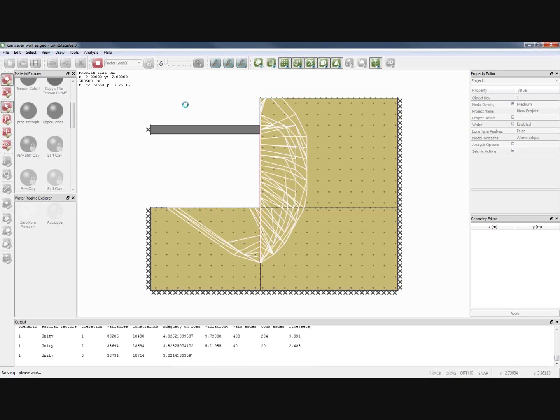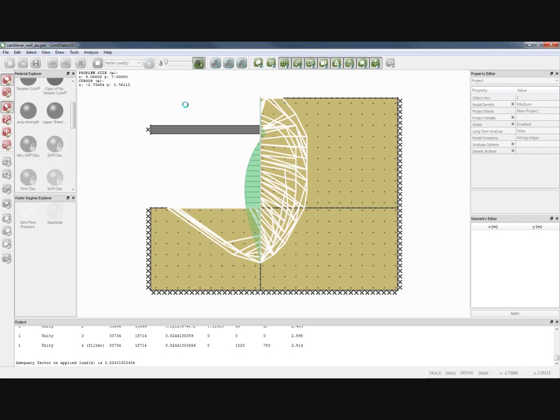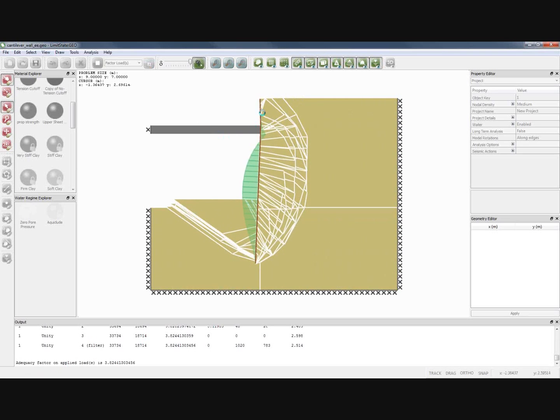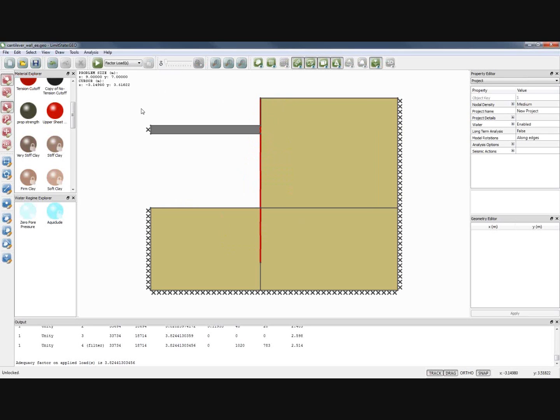And what happens then is that upper bit of the wall stays vertical, essentially, while the bottom part of the wall rotates. So up here, this part of the wall is actually rotating slightly, but if you put it in that sort of value, then you're basically taking the influence of that out from the analysis, which, as I said, in many cases it doesn't really matter if the prop's quite near the top of the wall, but can be something to think about. Okay, that's